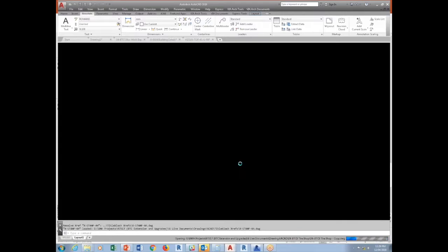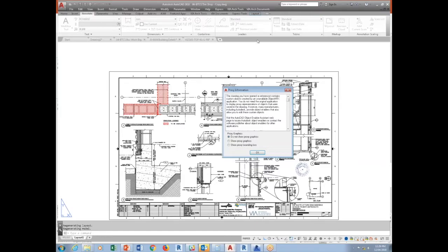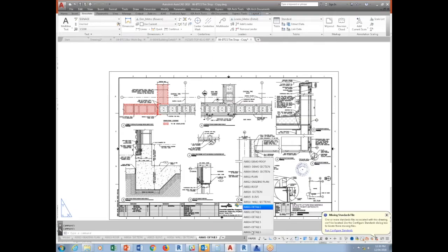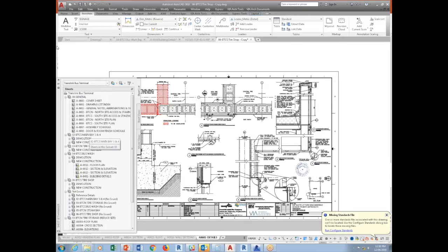You will get into this issue with AutoCAD where some guy is saying, oh, I received a file from consultants, and I want you to print all the drawings, okay? So sometimes what you end up getting is that you have a lot of tabs, okay? Like probably a lot of these drawings just to print out. You can go to each individual drawing and print each one individually, but that is a complete waste of time, okay? I'm going to show you one way to do this. Okay, to do this, what you could do is use what's known as the Sheet Set Manager, SSM, okay?